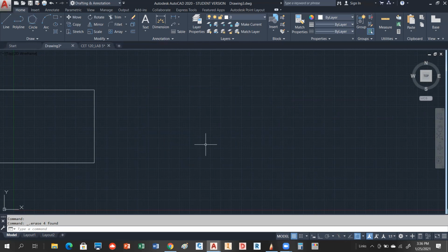By the way, you're probably not going to use a polygon, or a polyline, I'm sorry, a rectangle all that much, but we'll use it for a few things. It's nice for doing borders and those kinds of things. Okay, so let's look at some of the other options here. I'm going to take this width. My width was a little small. I'm going to beef that up just a little bit. So if you want to beef your width up, if you're following along, I'm going to maybe make that about 0.4.